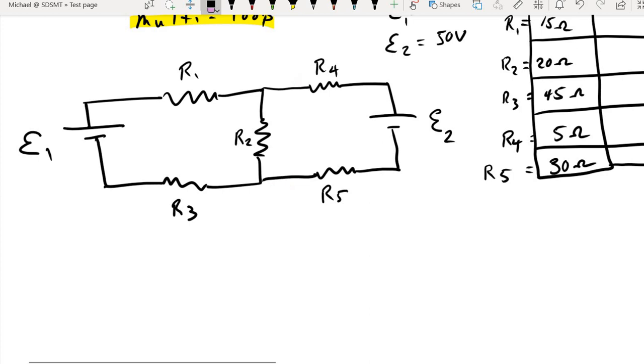So what about parallel? Well, it looks like resistor 1 and resistor 3 are in parallel, but to meet the condition of being connected in parallel, the heads and the tails of the resistors have to be connected together. And right here I've got an EMF in the way, and over here I've got a resistor in the way, so I don't meet the condition of parallel either.